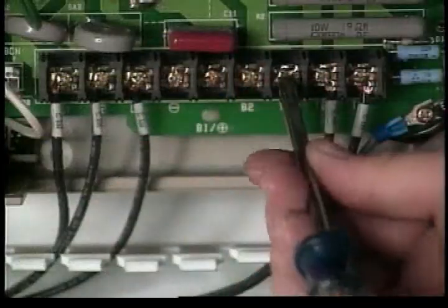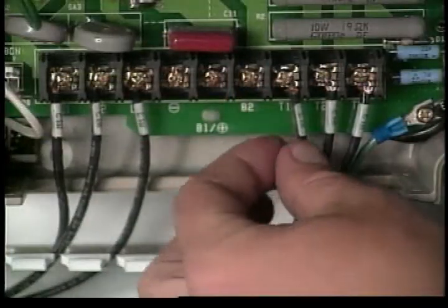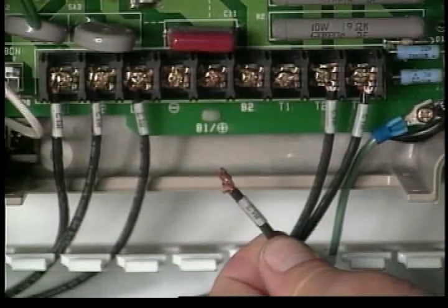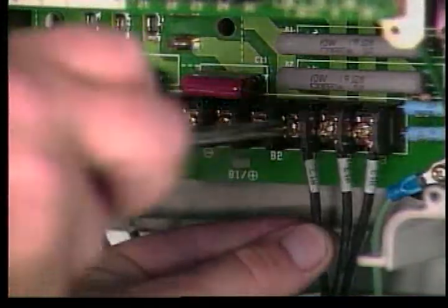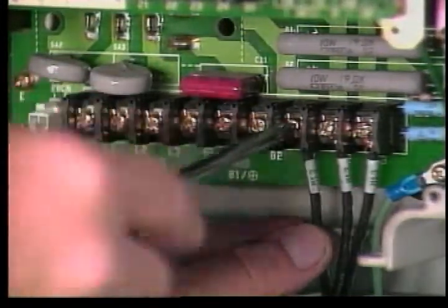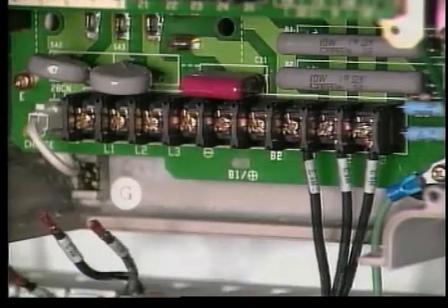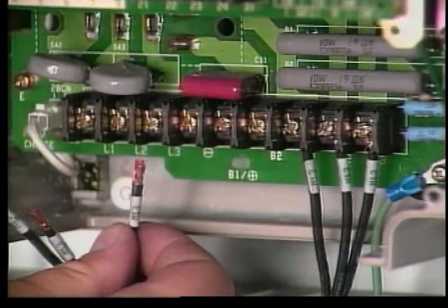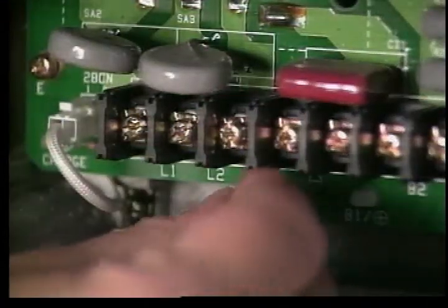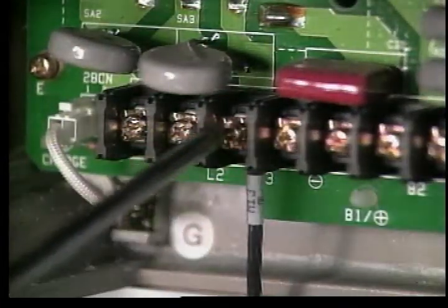If the inverter must be replaced, be sure each wire is identified and labeled before you remove it from the terminal strip. Then, when installing the replacement, make sure you fasten the correct wires to the correct terminals on the terminal strip. Be especially careful with the incoming AC lines. If you mistakenly wire three-phase power to the motor terminals, the inverter will be severely damaged when you apply power.